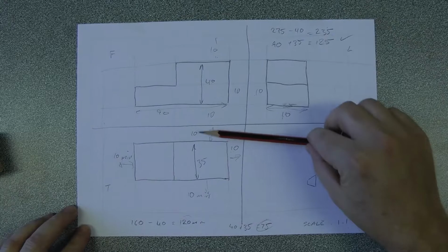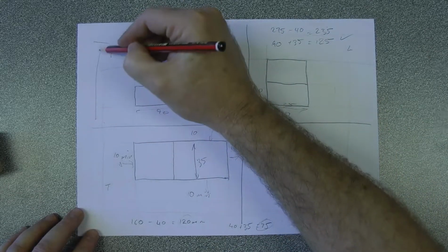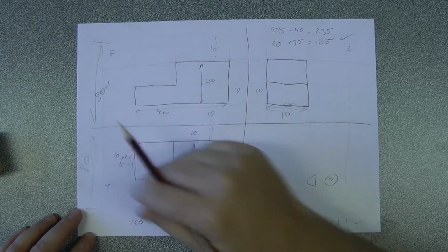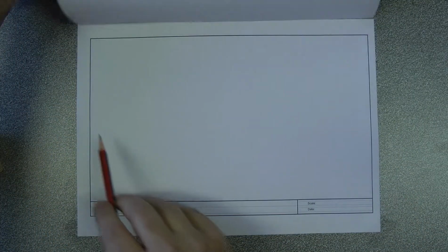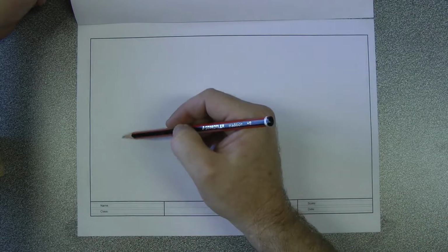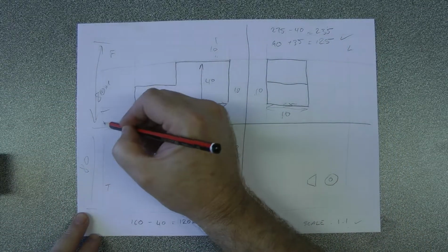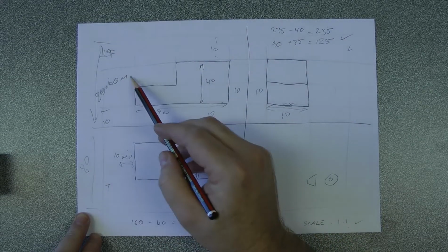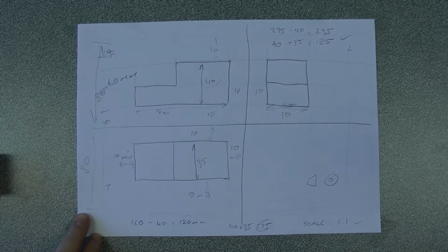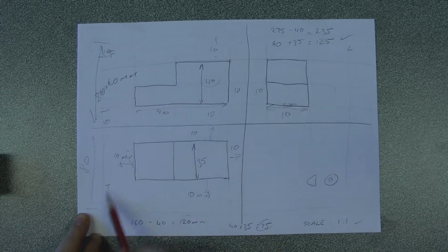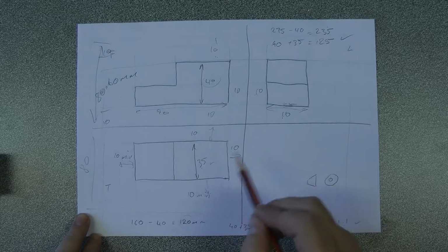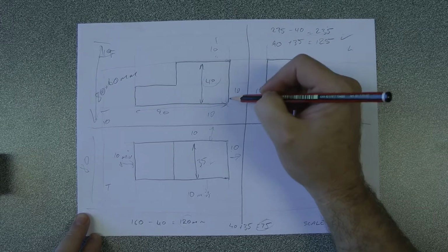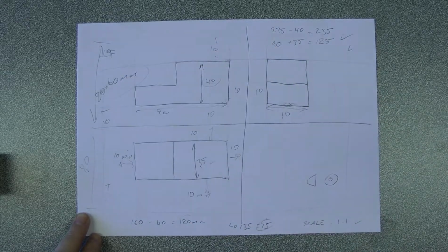If I put this in the center firstly, I'm going to be measuring down 80 millimeters, and I'm going to be measuring 80 millimeters. So that means I'm putting my line across the center here, 80 millimeters above and 80 millimeters below. I've got to take off at least 10, so I've got 60 millimeters in the middle. Now 60 millimeters is bigger than 40, I don't have a problem. I have the same 60 millimeters here, it's bigger than 35, I don't have a problem. I can put this in the center. But if this height was 100 millimeters, it would be bigger than my 60 millimeters.